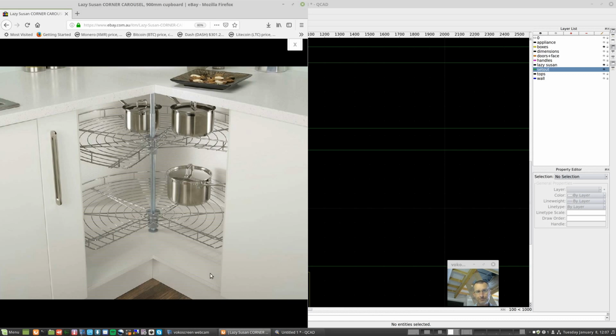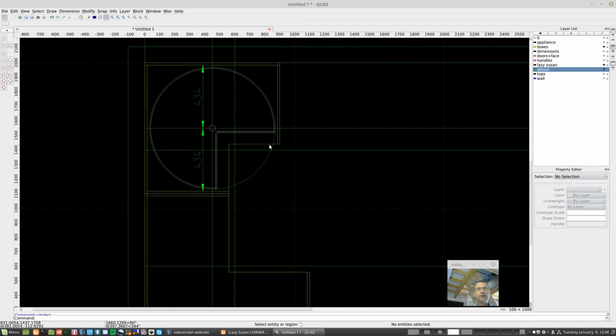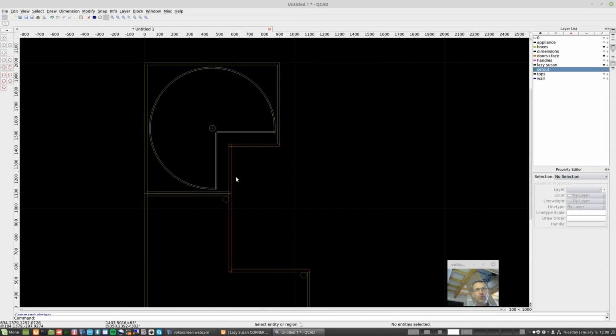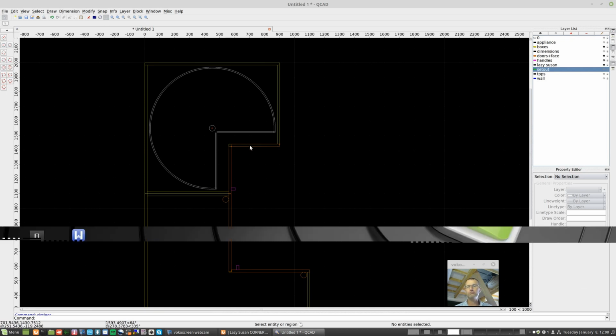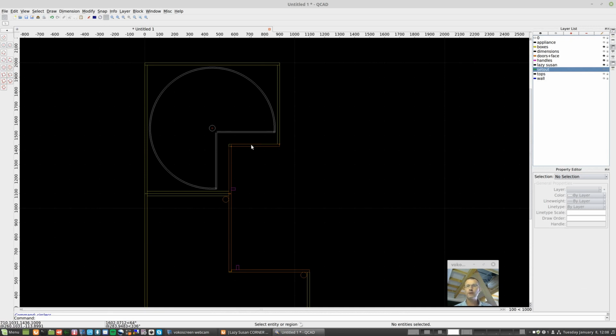If you've got a pair of doors hung together, such as in this configuration, where are our doors? Turn that off again. Where you've got this door hung off, then the handle's on. So we've got this door hung off that door. This door will actually be twisting that door. If you look at any examples, you don't have to believe me, just look around. You've probably got them in your own home. This door will twist that door. So assuming the hinges are happy with that strain, this door will basically have a problem because that door will twist.